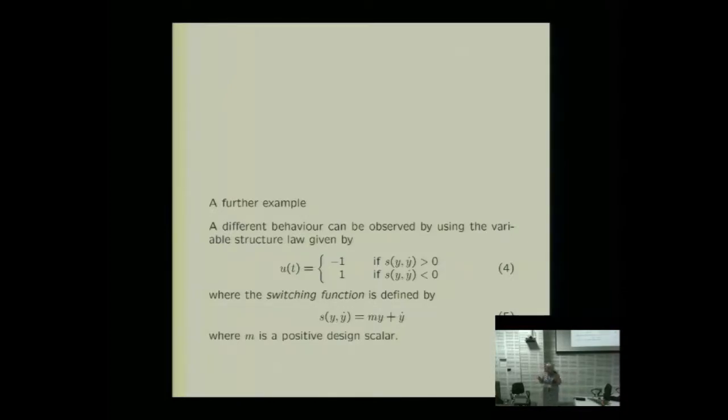And this comes very, very naturally by using a simple relay as the control. Notice we've made a change from what we did with the variable structure system. With the variable structure system, we were defining the performance based on the controllers we'd picked. The first thing to realize about sliding mode controllers, which many people who pick them up, we see many people in the literature who pick up sliding mode controllers as a tool. They have a particular problem and they try and apply it. But they don't realize that for a sliding mode controller, it isn't the controller that's giving us the performance.